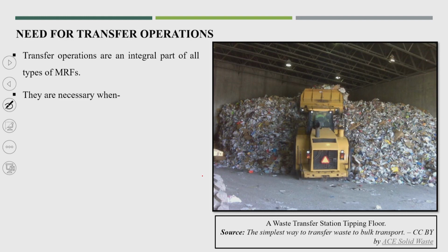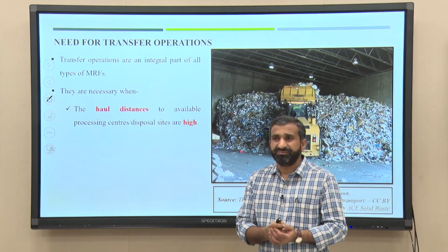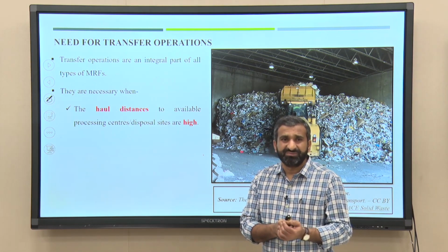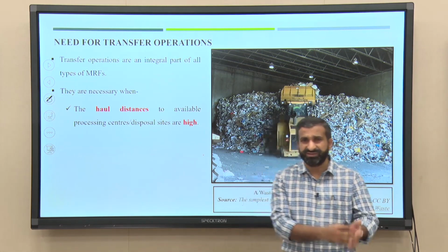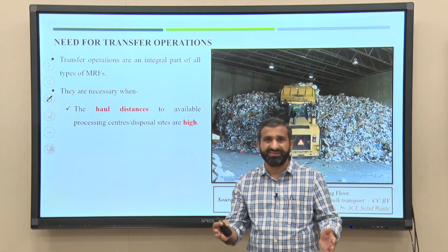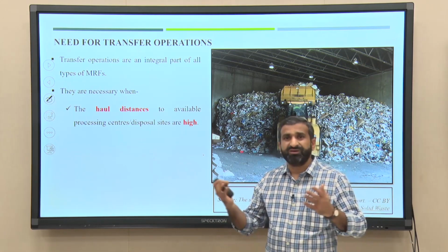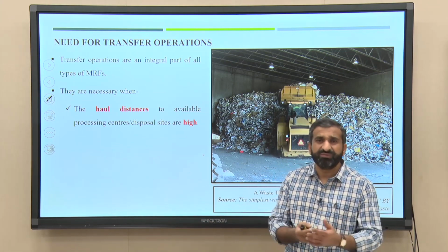Transfer stations are necessary when the haul distance to the available processing center or disposal sites is high. If the haul distance is high, you can ask, sir, high means what? It depends on the city, the distance. 10 kilometers, up to 20 kilometers, even 25 kilometers of traveling in a city is possible, and if you have a proper road where these larger vehicles can travel, it will be economical.